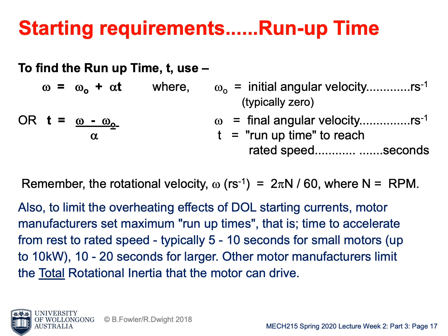So this is actually something some motor manufacturers will limit, how long this T can be for starting. If the run-up time is longer than this T, the motor will be overheated. So this number is typically 10-20 seconds, not allowed to be running too long.